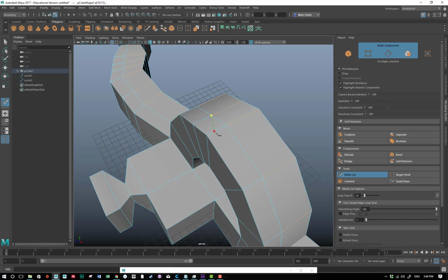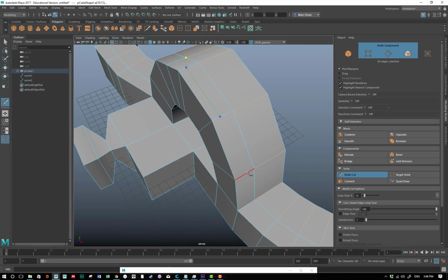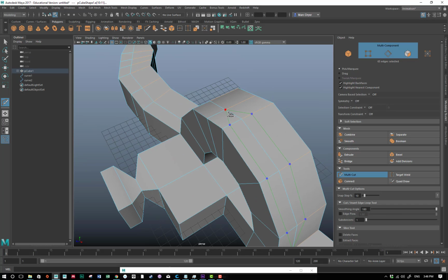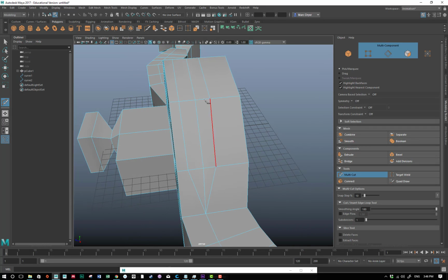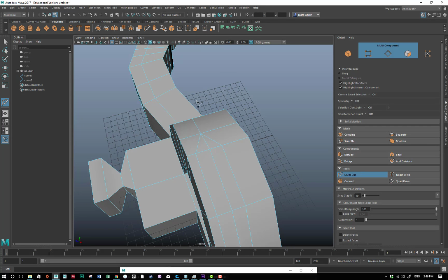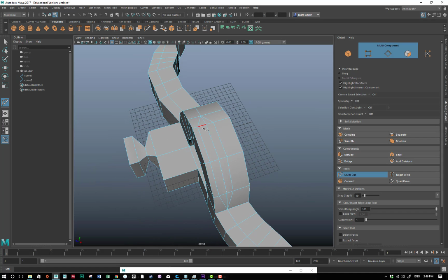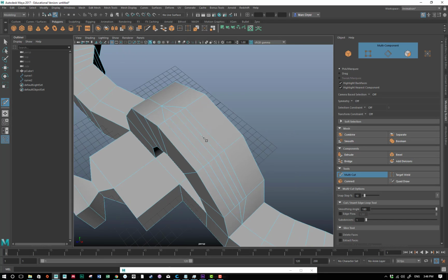Start with a vertex, go to an edge, edge, edge, back to a vertex, cut an edge, edge, and then close it at that vertex. Hit enter. And now what this does is it allows us to just add some local geometry. And then I might cut this again, so I still have the tool active. And now if I want to finish the tool and then relaunch it, I hit Y on the keyboard. Enter to finish. So what does this allow us to do?